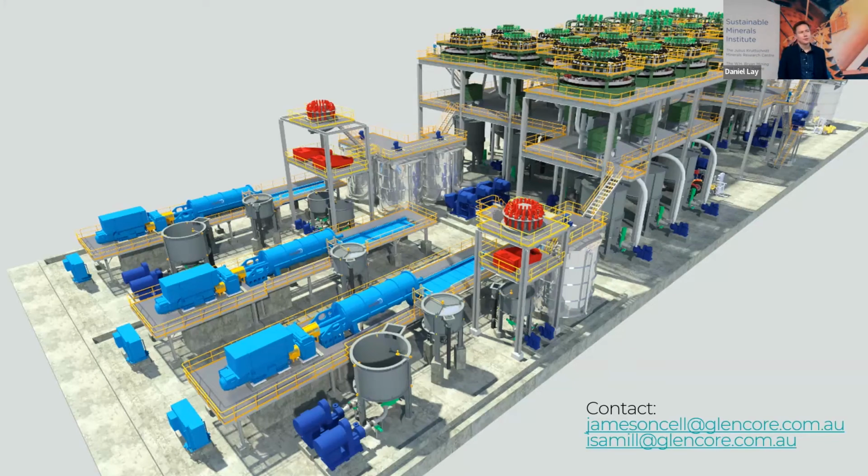Yeah. So look, I think that the choice of your type of separation in coal is going to be very dependent on the mineral that you are processing. So, you know, if you see in your float sink analysis a significant amount of low ash material that you can get out with gravity separation, you would apply gravity separation. Whereas if you only see that sort of low ash product being achievable with flotation, then you would apply a flotation cell.